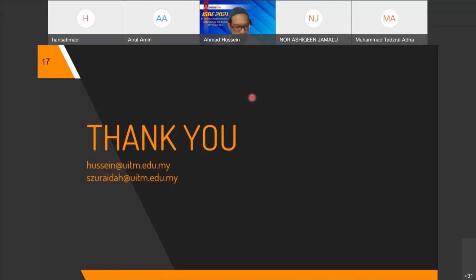Dr. Hussein, mashallah, your research is very good. Just curious to know, how do you say that having the vane will improve the stability? Basically we anticipate that with the vanes, the flow will impart angular momentum to the rocket and cause the rocket to spin. So it will stabilize through the spinning motion of the rocket, also known as spin stabilization.